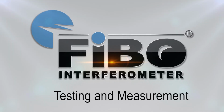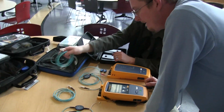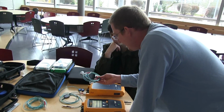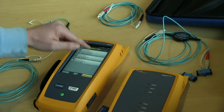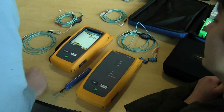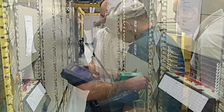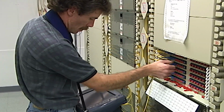Now that we have a better understanding of fiber optics, connectors, and some of the ways network performance can be degraded, what tests and measurements can be made to verify performance and find sources of trouble? The most common tests performed on fiber networks are loss measurements using a light source and power meter, and fiber span analysis using an optical time domain reflectometer, or OTDR. However, actual test methods and equipment used will depend on the application, such as acceptance testing, quality assurance, and documentation or troubleshooting and restoration.